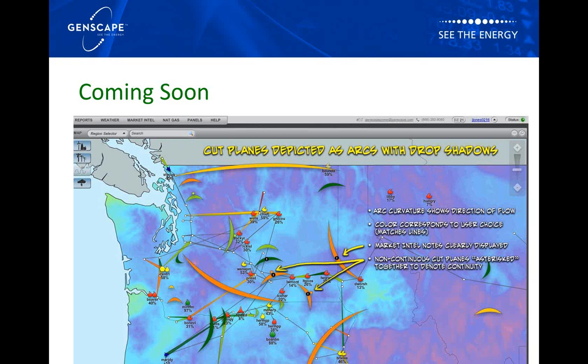Yeah, so I think there's benefits to using both. I typically favor using the percentage of the limit. That's typically the best way for us to identify which lines are close to overloading. If you look at PJM, similar to the interface screen on eData, I think a lot of people use it in a similar fashion to that. They look at the flow and they can compare it to the limit. So looking at the line as a percentage of the limit, that's really a good indicator of seeing where some of the most sensitive pieces are.